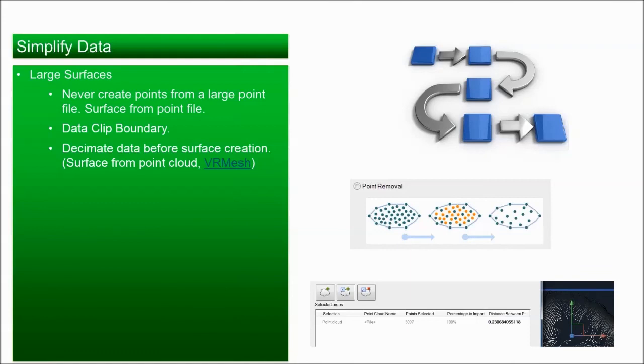It's very likely that those 20 million remaining points are very close to each other, maybe a couple centimeters, right? Traditionally, surveyors will walk 5, 10, maybe 20 meters in between shots. But the data that we get now from LiDAR and from scans can be millimeters or centimeters apart. But typically, we don't need that kind of density. So, further decimate it by removing points down to something that's usable. So instead of 20 million points, maybe we can get away with 2 million. And that should be no problem for Civil 3D.